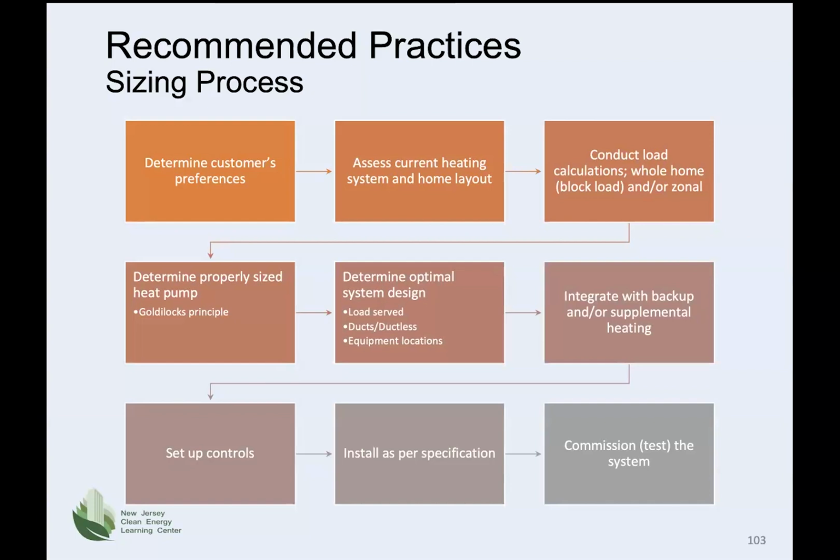And then the optimal system design, which loads are going to be served, whether it's going to be ductless or ducted, and where to locate the equipment. Then, as far as controls are concerned, if there is a backup heating or supplemental heating, they have to be integrated with the heat pump system. And then the controls are set up and the set points are determined, and the installation is performed in accordance with manufacturer's specifications. And then lastly, the system is tested and commissioned.